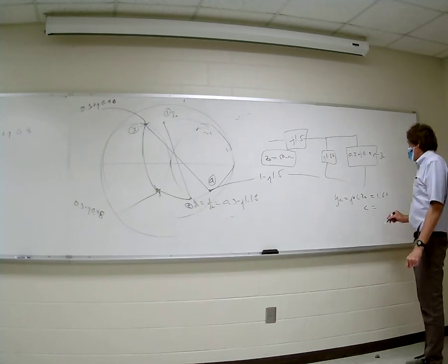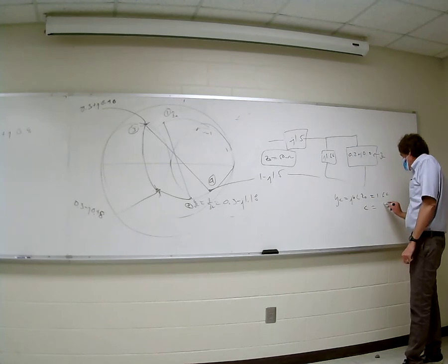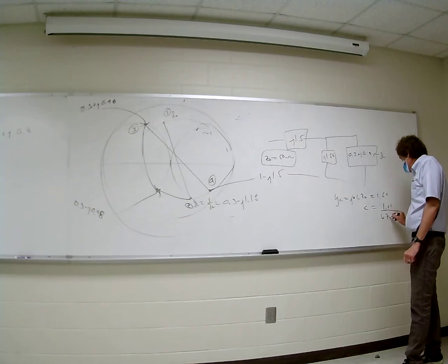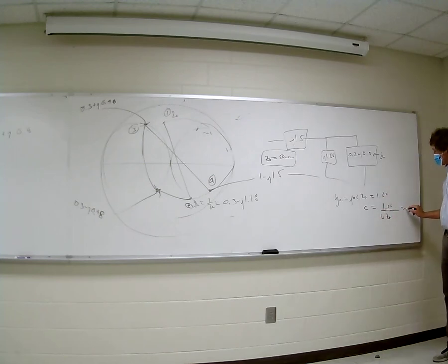All right, so if I wanted C for this, what happens? Well, I just take 1.66, right? And divide it by omega times Z naught, and lo and behold, I have my C value. What is that? If I say Z naught is 50, omega is 2 pi f, right?